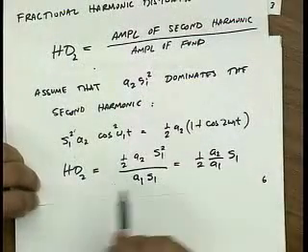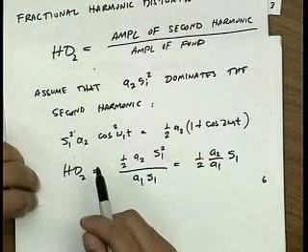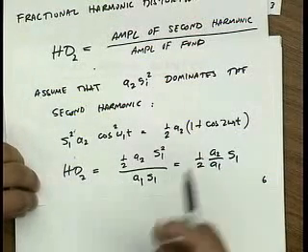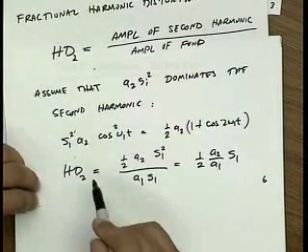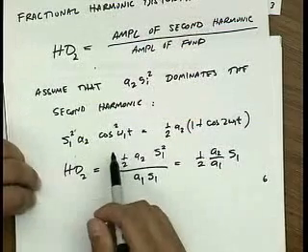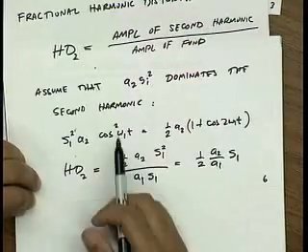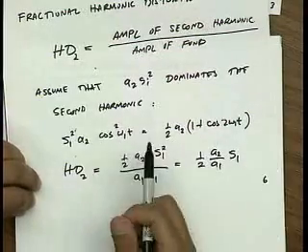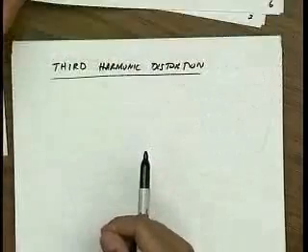Well, there's very likely, if you're watching 100 megahertz, there's going to be another channel at 200 megahertz someone's watching. So again, second harmonic matters. You might be dealing with an ultra-wideband system where second harmonic falls in band. Or something as simple as an audio amplifier, right? If the musician intended you to hear 5 kilohertz and you're outputting 10 kilohertz, again, it's not a very nice thing to do. All right.